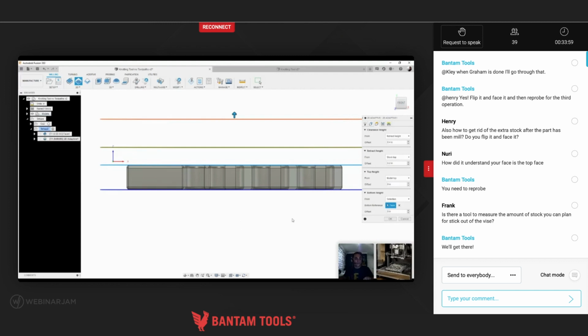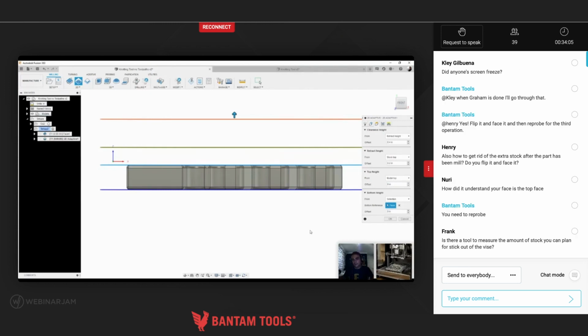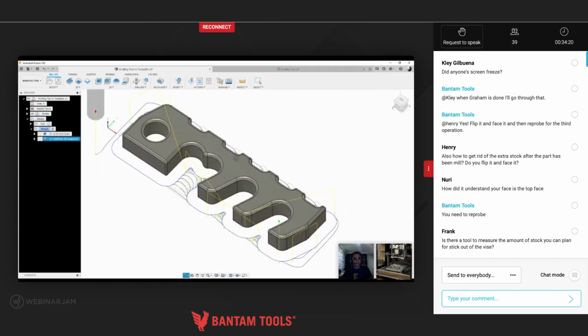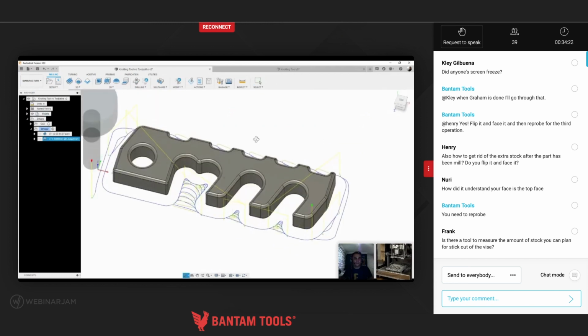However, because obviously there's always slight bits of inaccuracies, and we don't really want to be machining that close to the face here, we want to give ourselves a little bit extra. So what we'll do is we'll add an additional offset here, say of 0.5. Oops, sorry, 0.05. Press OK, and you can see here it's created our adaptive clearing pattern here.